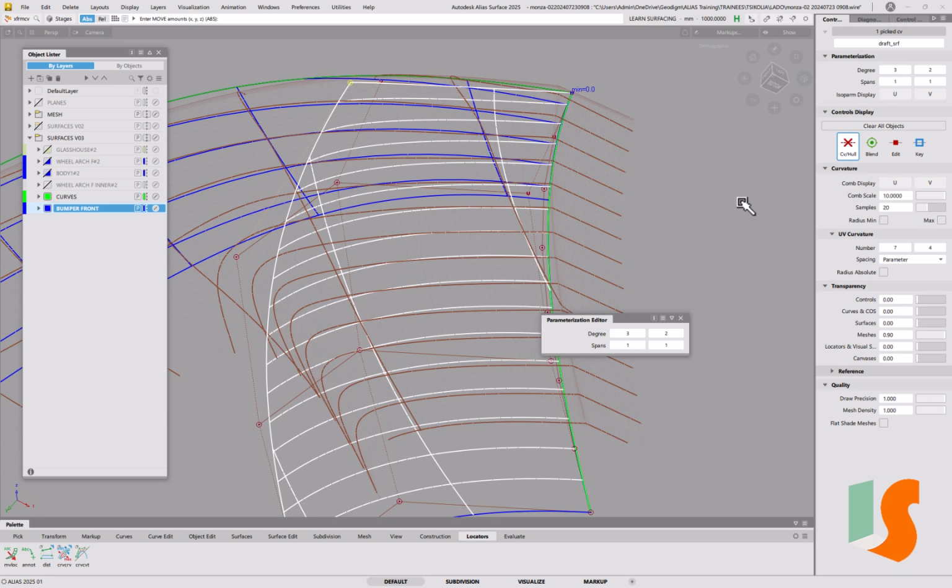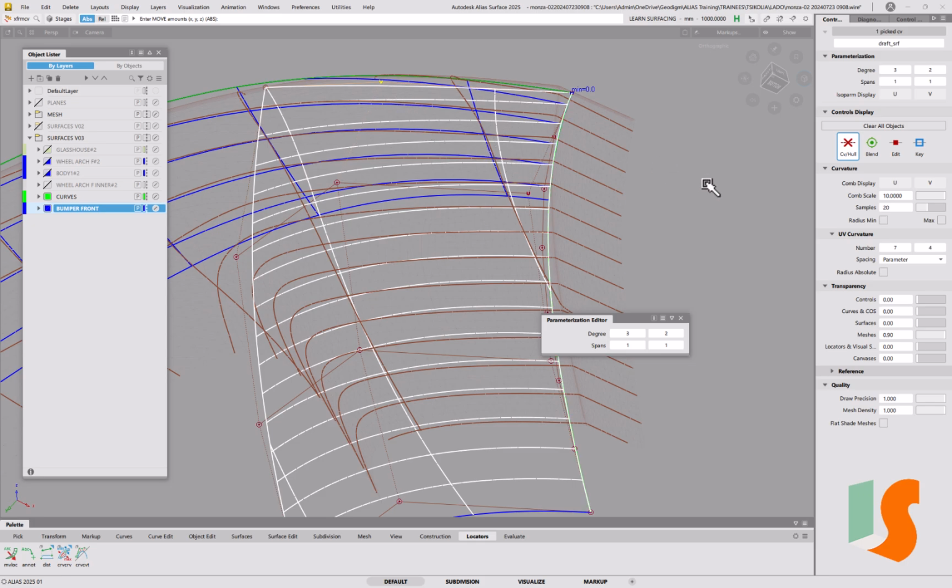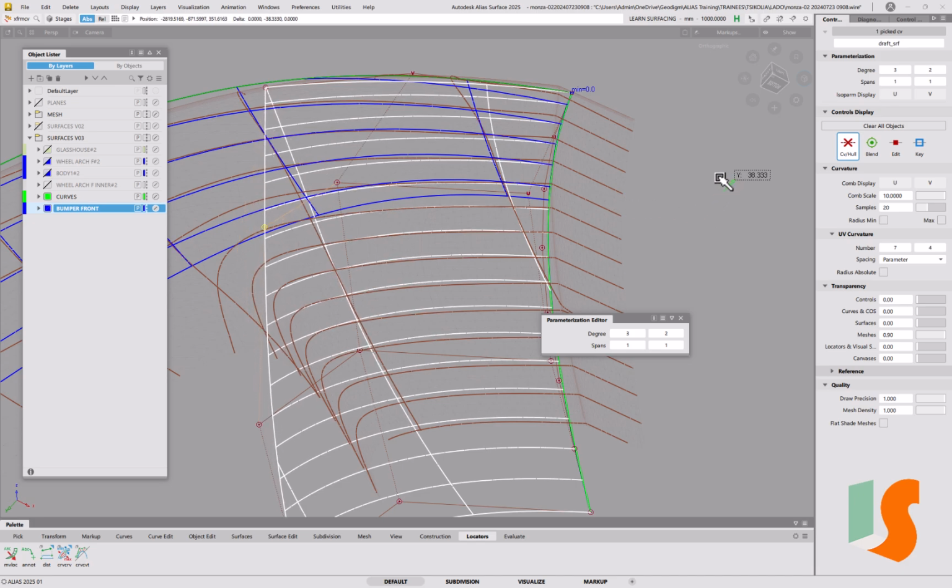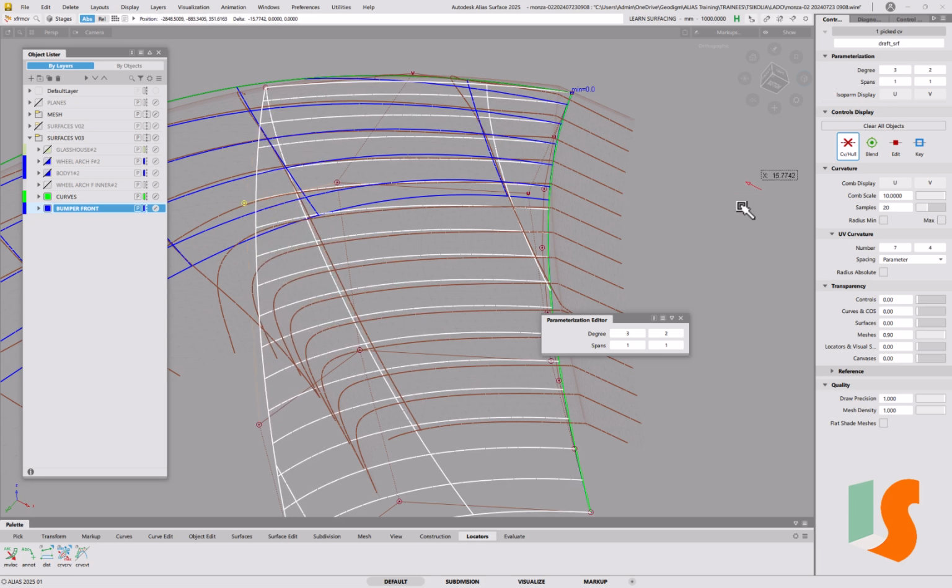And so we can either pull that in the Y direction and then push it out in the X so that the spacing gets a bit more, it needs to be a bit more uniform up here, to be honest, because that's more of a constant arc type shape. So maybe this point could go back. We'll have to look at the side view to see what this is looking like, but I'm moving it in the X and the Y, bearing in mind that this disappears under this surface here. So this is where it's tricky, because we don't really know where one surface ends and the other one finishes. So maybe we should be looking at sections down here a bit more than the ones higher up.